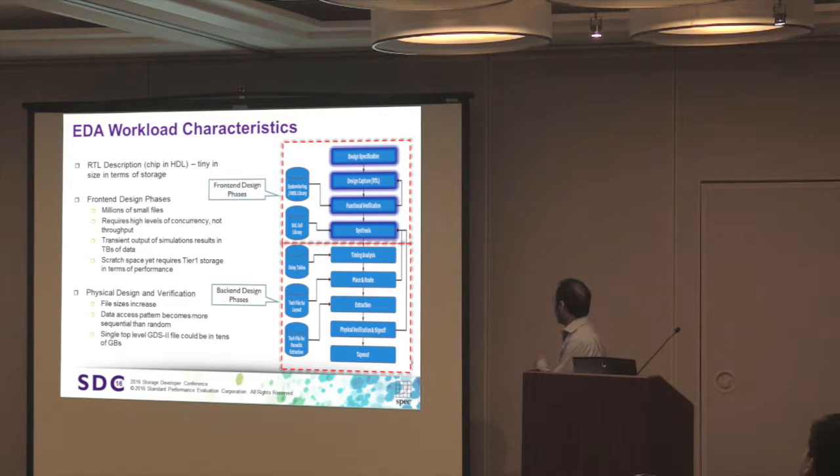After that, you say, okay, I have described an adder, then I'm going to make sure I actually get that to functionally work as designed. So I would say 2 plus 2 and I anticipate 4. I would say 2 plus 3 and I anticipate 5. So it goes through a functional verification stage. Then you synthesize the design. Synthesis could be either on the back end or the front end. But think of synthesis as now bringing the design to the gate level, right? You're compiling your design.